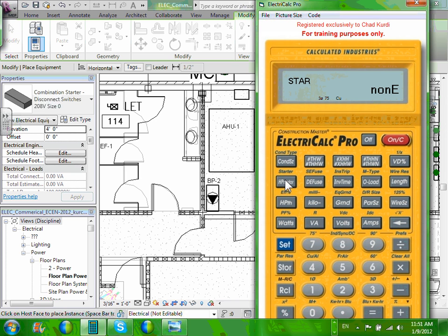Okay. If you guys go, where's the motor here? Branch, here you go. Right here. Can you guys go to page 6-4, DeWalt, 6-4. It will tell you if it's a 208 system and it's the 2 horsepower, you need 0. You need 0, right? Nick, am I right? So do they say just 0? NEMA 0. NEMA 0. And NEMA 0 for the other one? Yeah, only if it's needed, please. The reason I'm dropping it is because it's needed. So this is NEMA. I don't know why the calculator is not catching it. It's NEMA 0.